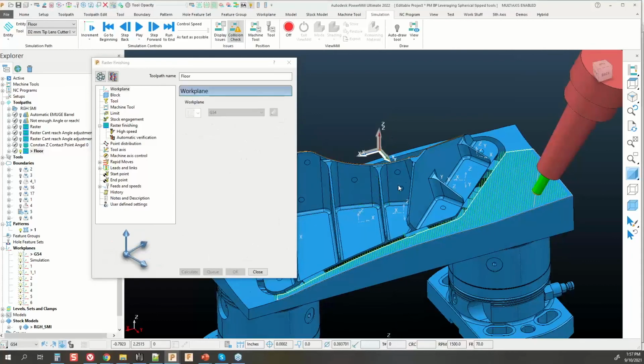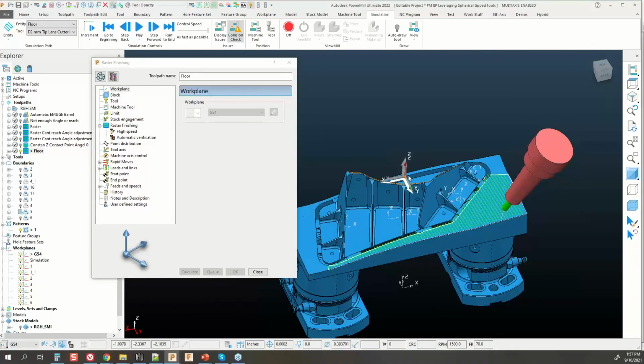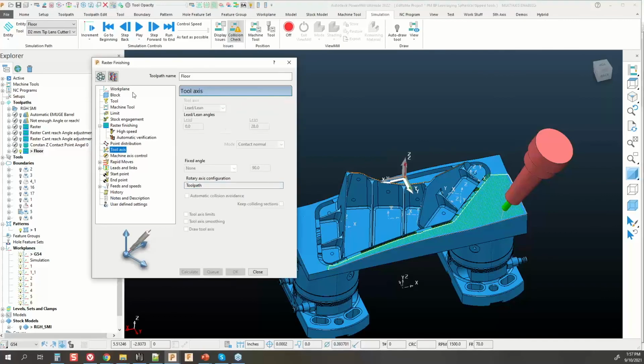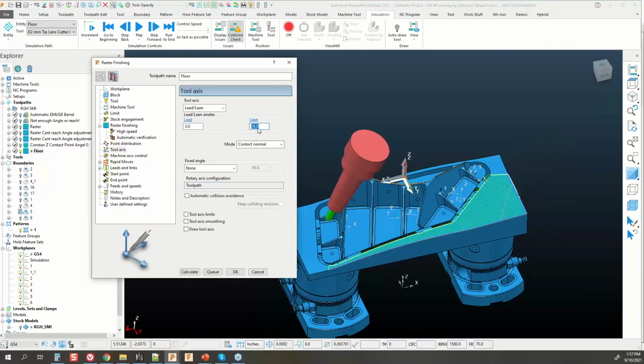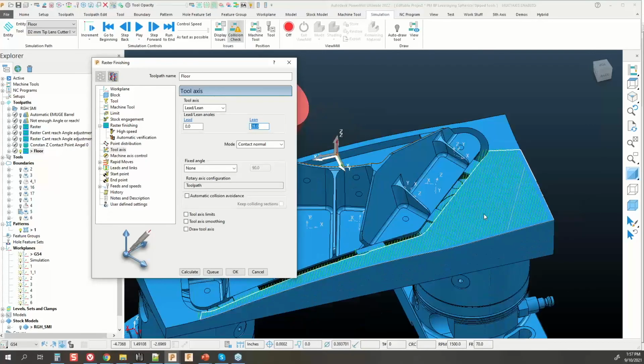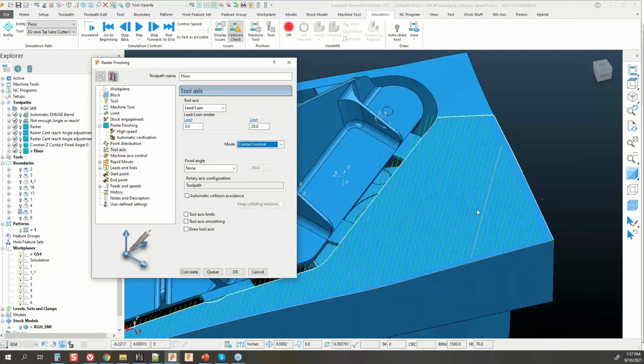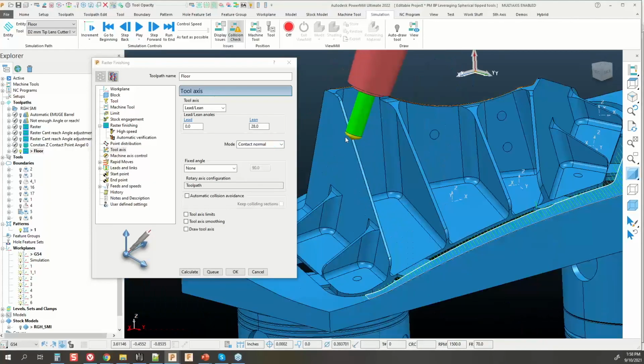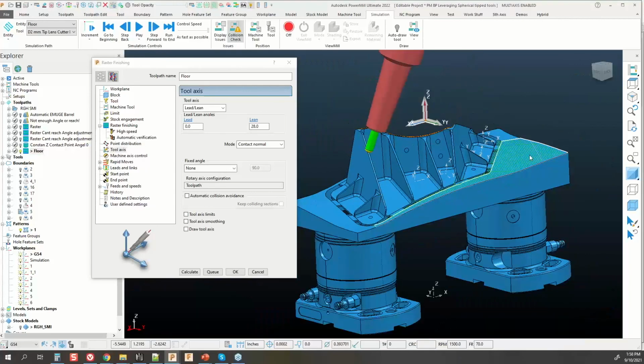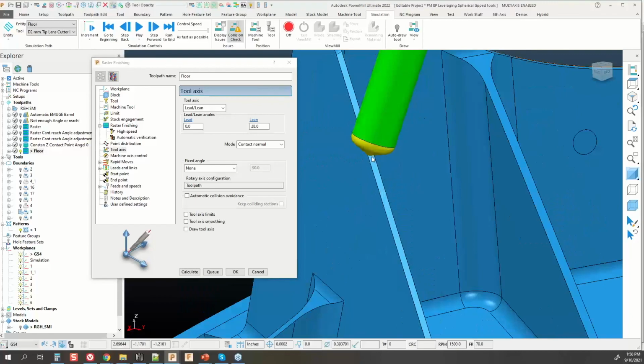With this setup and these settings, I did come from a vertical position here for the toolpath, just to go in the tool axis settings here at lead link of 28 degrees. Now this was something that worked out direct, and it's important to note that that contact normal to the surface is what I'm looking for. We typically don't want to do a vertical in this situation for our tool axis, mostly because you're tilting the angle of the sphere of the tool from the surface itself. We just need to determine whether or not that's actually coming directly from the angle of the tip of the tool, or along that shank.